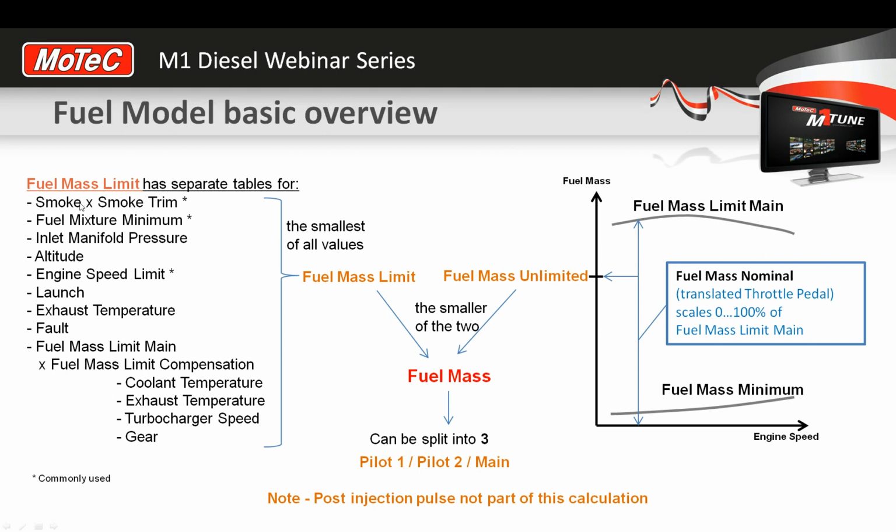Alright, so that smoke table allows you to do that tuning using milligram numbers of fuel, using physical units, the unit of measurement being milligrams. Now the fuel mixture minimum table is virtually the identical thing, only you can actually type in your aim lambda, your aim fuel mixture, and provided your injector calibrations are perfect, which is almost impossible, I'm sorry to say, but if they were perfect, then you could simply type in lambda 1.2 and then the system, if all calibrations are correct, would just know what the airflow was, what the fueling is, and just maintain fueling to suit.